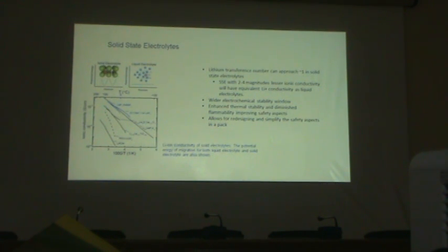In that case, these solid state electrolytes might prove a point, because if you want to use it in an aqueous medium, leaving the non-aqueous electrolyte, you can shield the lithium metal using this particular solid electrolyte and then proceed with the aqueous lithium cell. These kinds of proposals are there. So that is another advantage that these solid electrolytes provide.